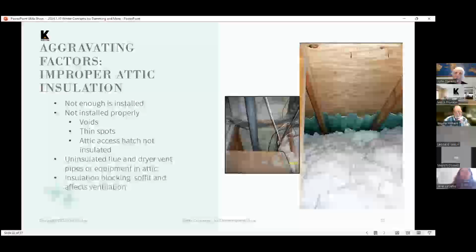So the baffles are put in, they compress the insulation down a little, and because of their shape, they allow the air to flow up from the soffit vents and into the general attic space, and then out, of course, out the upper part of the roof.